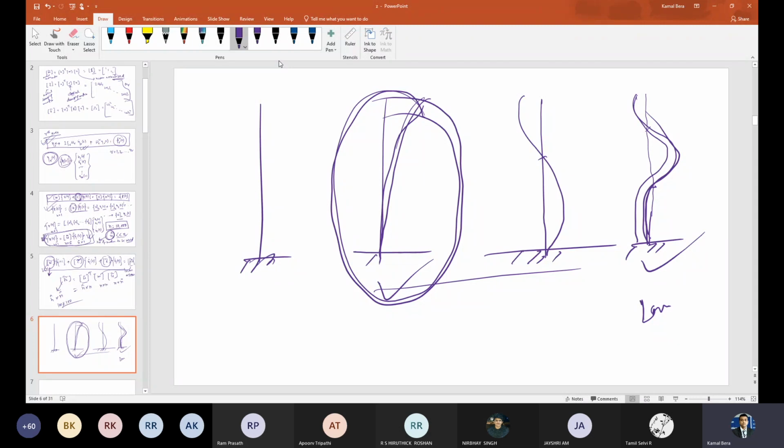In a continuous system, the number of degrees of freedom is infinite. At each and every point there is a degree of freedom. But for this kind of cantilever beam or cantilever tower, the first 4 or 5 modes, I do not remember exactly, contribute more than 80% of the total response. Let's say the peak response is 100. We will get 80% of the response by considering only the first 4 modes for a cantilever system.